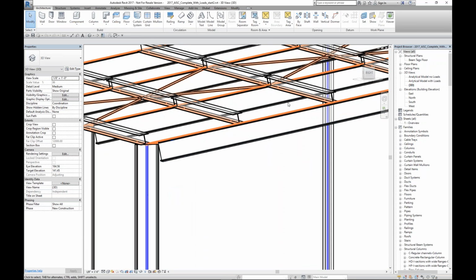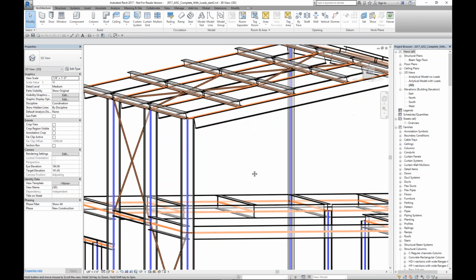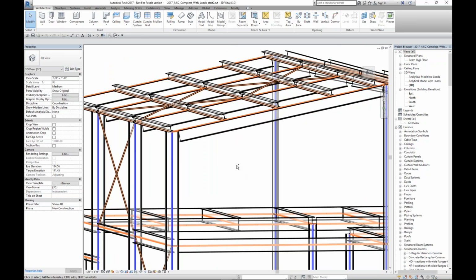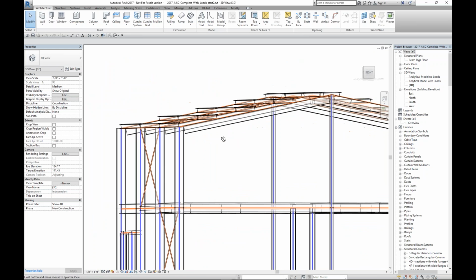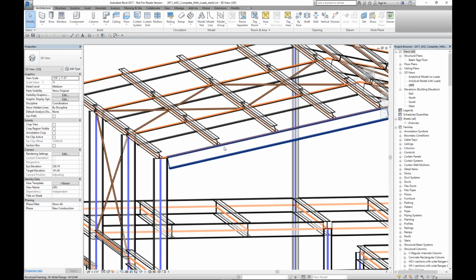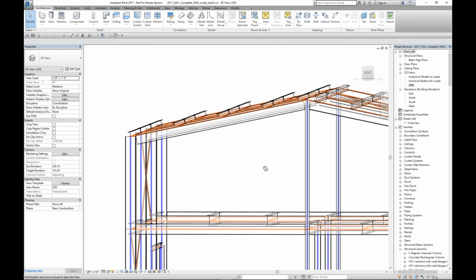If you don't do this, you might get rigid links. You might get also offsets that can be converted into what we call eccentricities in our software. It's then getting a little bit more complicated, and in general, engineers tend to like to keep it simple. So wherever you don't need eccentricities, we'll keep them out, and so I do here in this case.